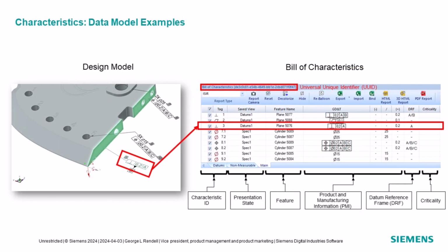Second slide gives you a little bit more graphics. As a designer or MCAD guy, I'm really familiar over here with the geometry. Obviously, we have the PMI types. With the characteristics, we'll have the ballooning and tracking that you see. Those things will be associated into a bill of characteristics. Those bill of characteristics will be associated to the PMI, PMI back to the geometry.